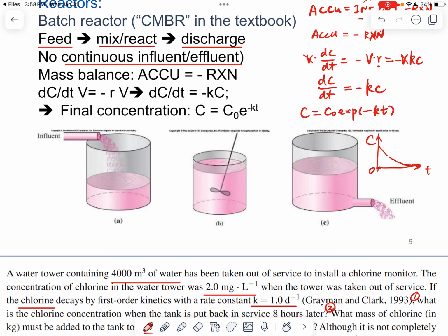We cannot do that because there should always be flow going through the wastewater treatment plant, right? So because of that, we have to use a flow reactor. Okay, so the batch reactor cannot hold any flow, right, or accommodate any flow. But in the actual situation where we are dealing with different types of reactants or different types of pollutions, we have to consider the continuous flow or to create this flow reactor.